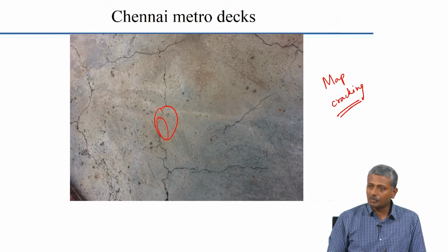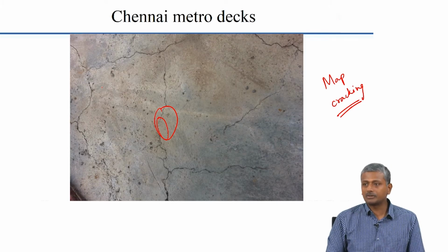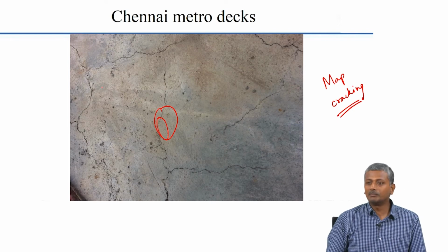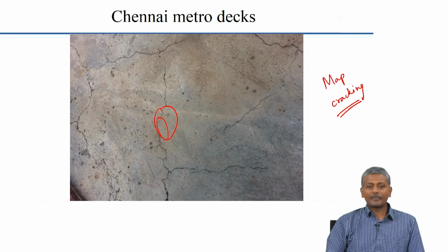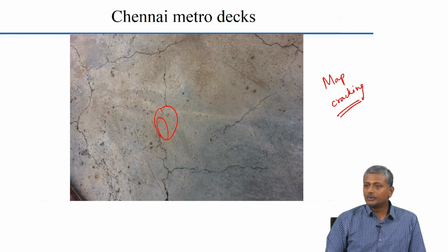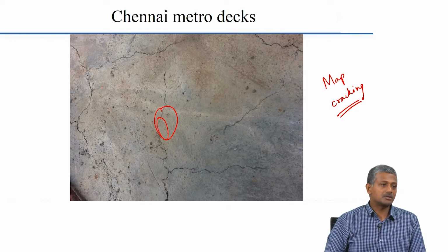But because of the length of the process, sometimes it went up to about 9 to 10 a.m. And this was actually being done in August. Okay. Chennai in August is quite warm, it is not cool by any means, because there has been no rain typically in August. So, in those hot temperatures, especially if it is accompanied by winds, you can have a lot of drying that happens from the surface, and that will lead to plastic shrinkage related problems.